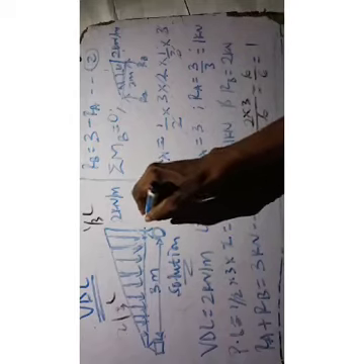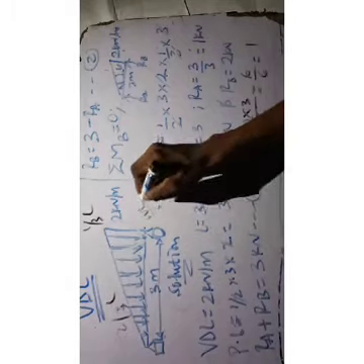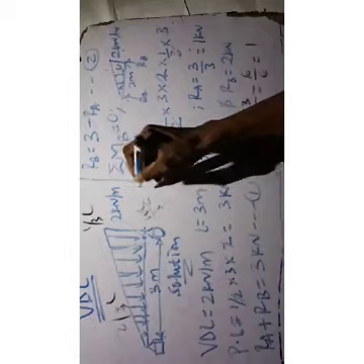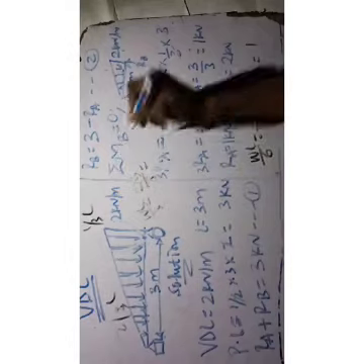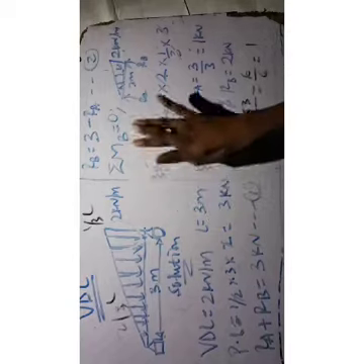Then this will cancel, you have 3. Then RA is where you have this. We can make use of this formula. And if you remember, your RB as well is WL over 3, right? So if you use WL over 3, W is 2, that will be 2 times 3 over 3, and that becomes 2. So you can find out that your RB is 2. Very cheap and very fast. You can just use that for a check. Okay, and we have our answer as 1 and 2.